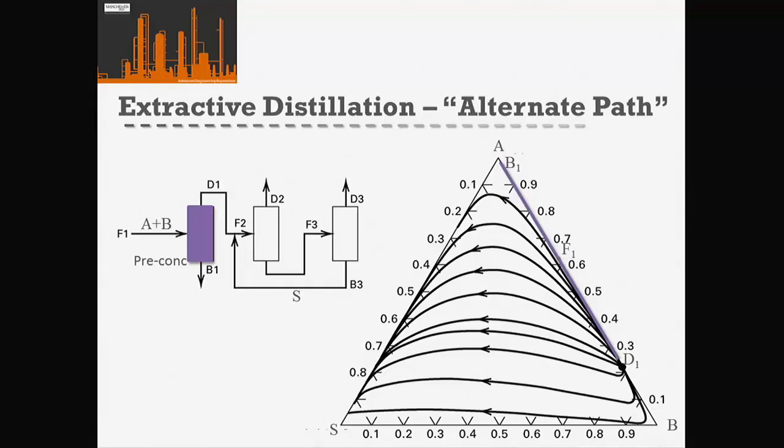Yeah. So when we're looking at the stage that has a recycle with the solvent in, we don't have such a high flow rate of material needing to be put in that system. Okay, because we've already extracted one of our pure components that we can actually get to. Okay, and that's the reason that this first column is often called a pre-concentrator column. Yeah. So we can draw all of these columns on this diagram, yeah.